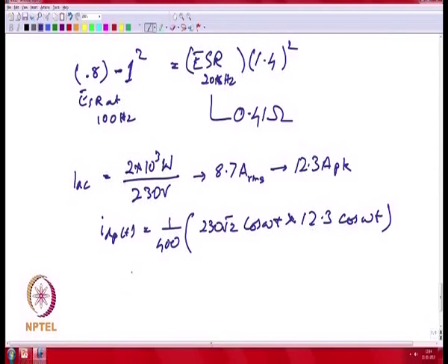So your IDC average DC current is 5 amps, and your IDCP at 100 hertz is 5 amps peak, which would correspond to 3.54 amps RMS.